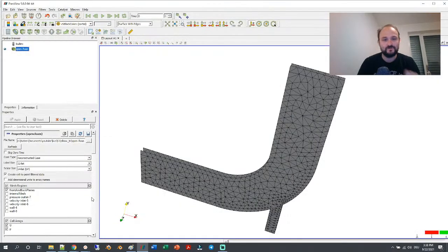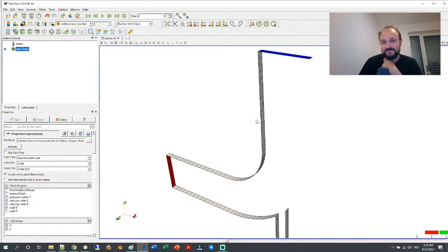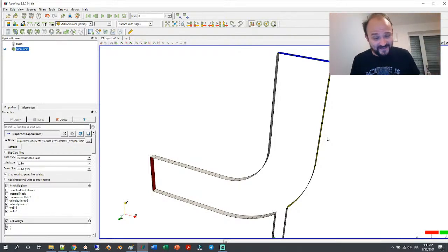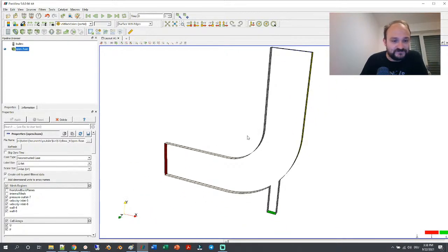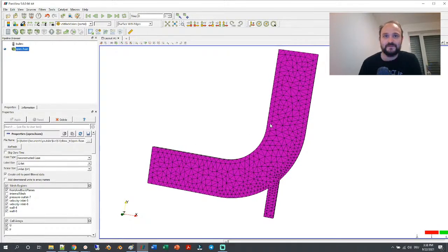Okay, maybe what I didn't show you are the walls. So the pressure outlet is, as I mentioned, this phase. Then we have our inlet here where we enter with 1 meter per second. Then the second inlet is here in the bottom where we enter with 3 meters per second in the Y direction. And we have wall 4, which are these boundaries, and then we have a wall 8 here. So this is given by OpenFOAM. This file has been around now for decades, I guess. So this is not something I created. This comes with OpenFOAM. In the next live stream, we will take a look at my version of this geometry. Okay, and the characteristic is that this is a triangulated case.